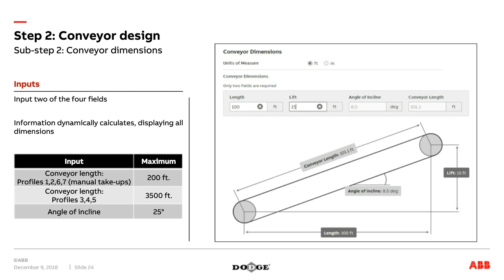You can quickly figure out what size motors, gearboxes, and pulleys should be in this application and compare it versus what's actually out there in operation to try to diagnose where some of the problems might be.